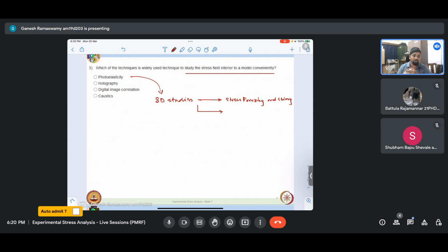The second one employs the concept of optical equivalence, which is nothing but you put a three-dimensional model and load it in a polariscope. There will be three unknown parameters; essentially the model will be introducing rotation and retardation at each and every point along its light path. So we will integrate the effects over the depth of the model along the light path, and substitute it with an equivalent rotator and retarder combination so that we get the same response.